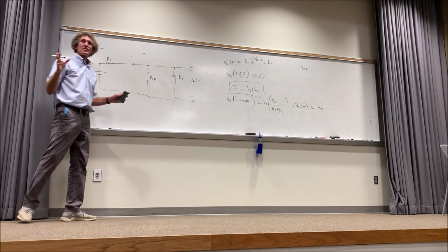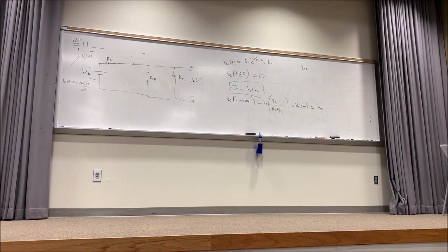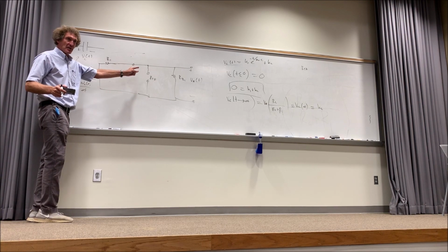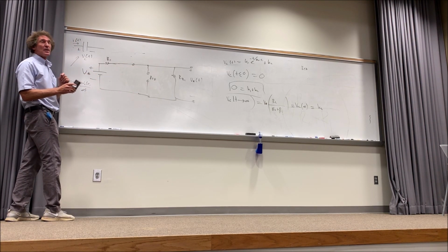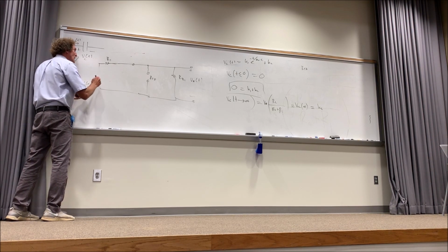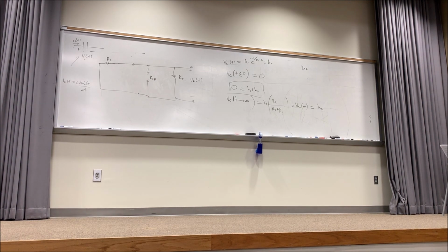Now how do you find R Thevenin? Listen carefully. Thevenin voltages, you know how to get. Thevenin resistance is always you turn off the sources, and you see what the resistance is across these two dangling leads where the capacitor was. Got me on that? So when I turn off the voltage, what does this become? Just a wire, short circuit, right? Now, take a look. How many see they're in parallel? Y'all see it in the back?